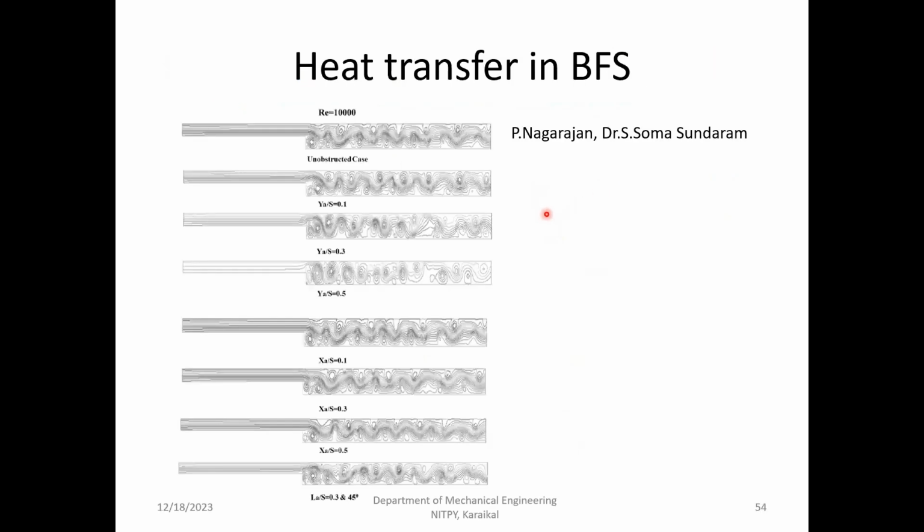Okay, so these are a few analyses and methods of presenting results done by my research scholars. This is a heat transfer problem. You can show streamline plots. And as I mentioned in the beginning of the slide, CFD was considered as colorful fluid dynamics. So generally my results will not have any colors unless required. This is going to be streamline plots. We can remove the filled option in contours, and you'll get patterns like this. You'll be getting only the contours. That also gives you a lot of information.